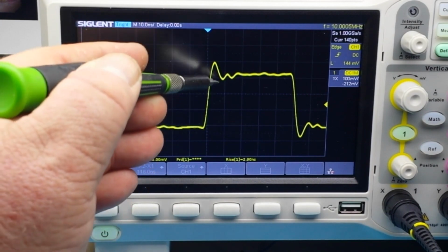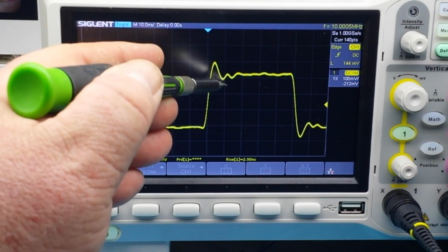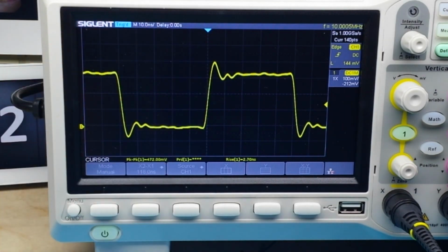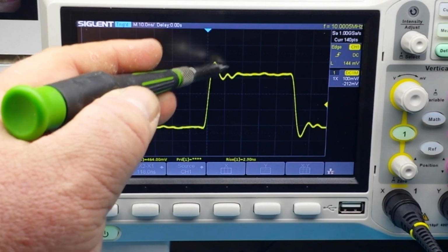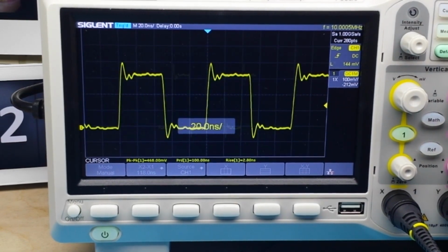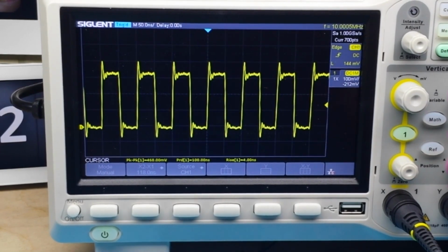So the signal climbs, it overshoots where it wants to go, then it undershoots, and then it overshoots, undershoots, overshoots. What's happening here is the signal is underdamped. This is damping here. See how it's very high, then lower, and then lower, and then finally it goes to where it wants to be. That's known as damping. So this is called ringing, and it simply means that your signal is underdamped. And it can be quite substantial.